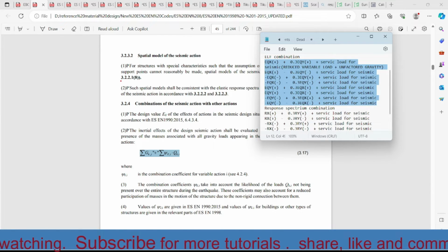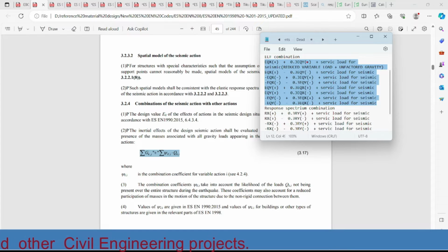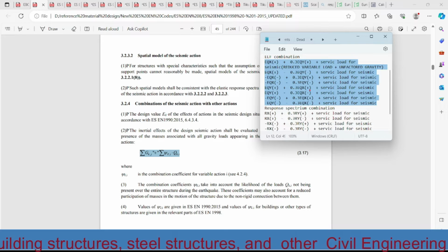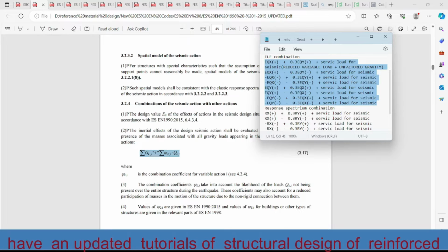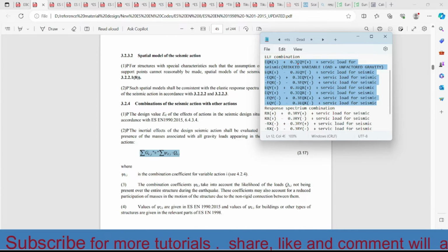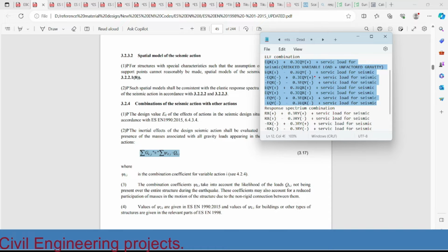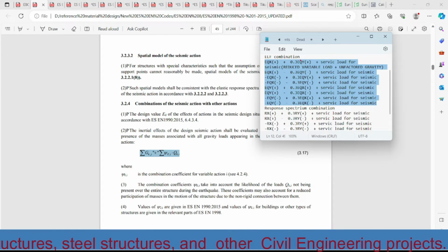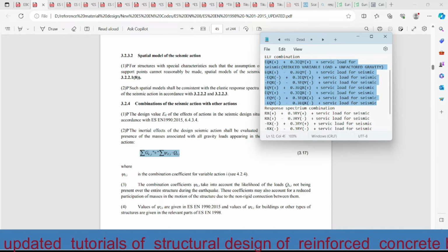Some guys said that we will have 32 combinations. They said there is a possibility of creating 32 load combinations for the static load case, and 32 load combinations for the dynamic load case, but the results will be repetitive. So to avoid the repetitive results and the time taken by ETABS for the analysis, we need to take these 8 combinations only.